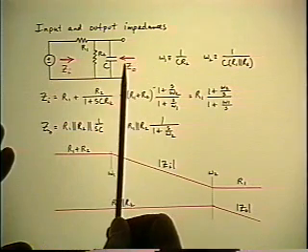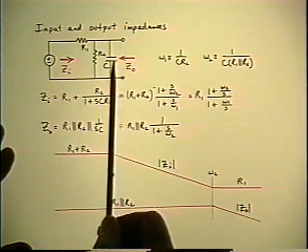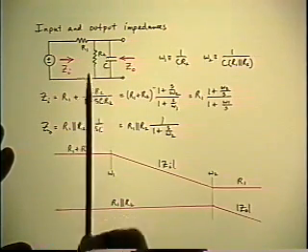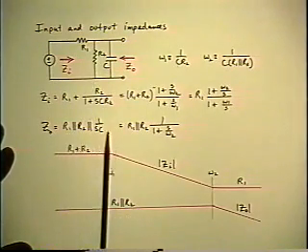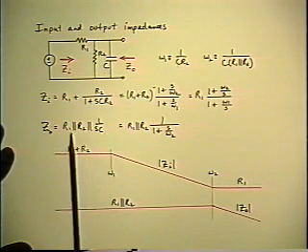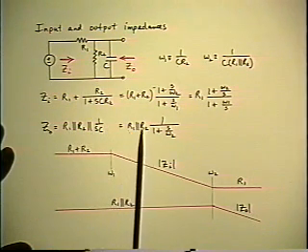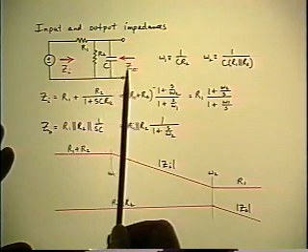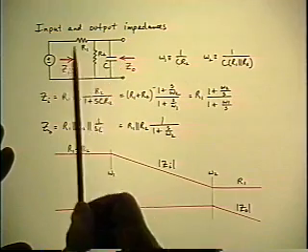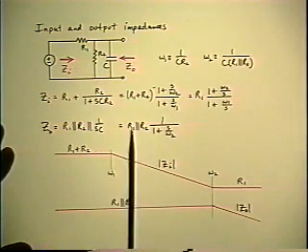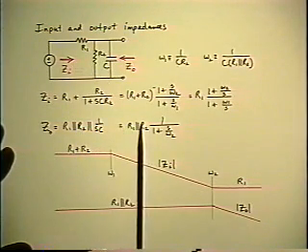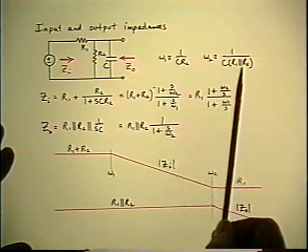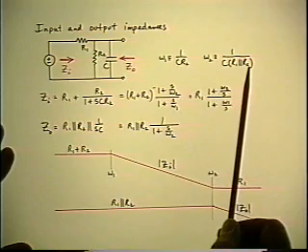So when you look in at the output, you're going to see the capacitor in parallel with the two resistors in parallel. So immediately the result is a triple parallel combination, and you keep the two resistors in parallel together as a single element, and the answer is the same as before. It's a parallel capacitor and a combined resistor, so the impedance is the effective resistor with a single pole at a frequency corresponding to the CR product.